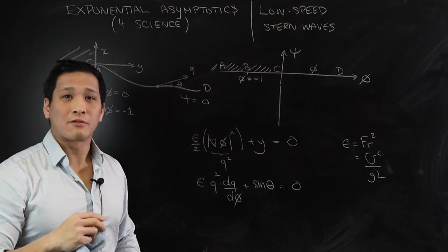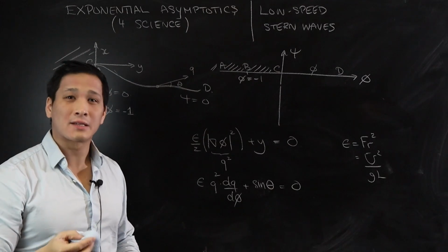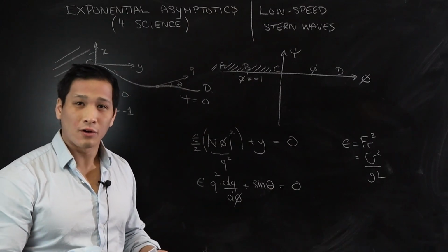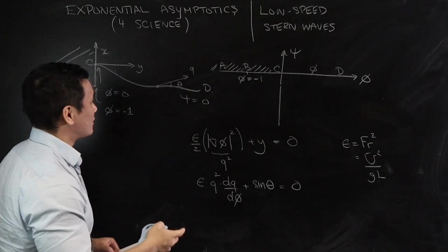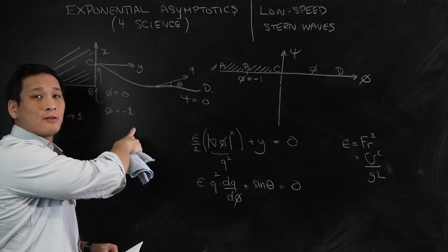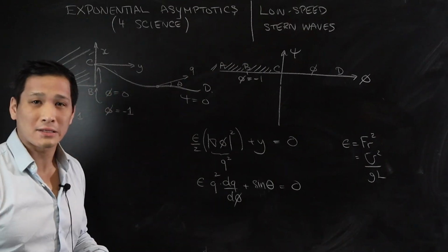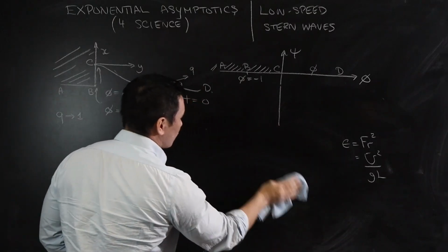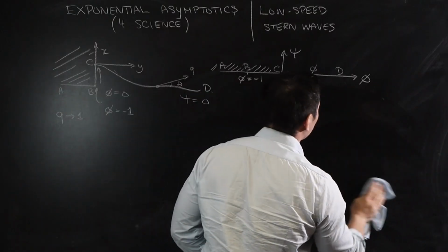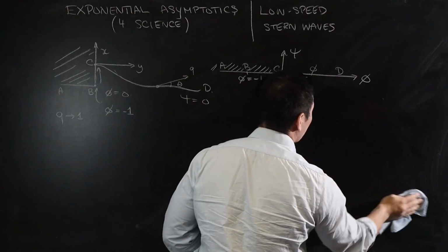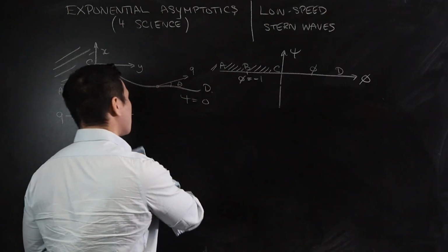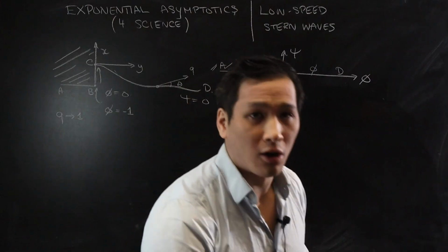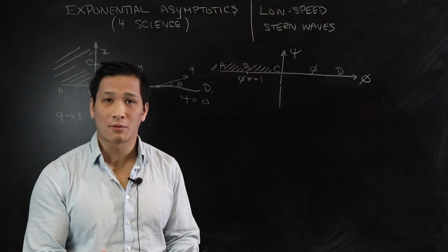We've got one set of equations. We need a second set of equations to close everything. And the set of equations that we haven't used so far is the fact that this is a potential fluid, and so it should satisfy Laplace's equation. When you deal with potential flow theory, Laplace's equation is often shown to be equivalent to an integral along the boundaries of your problem.